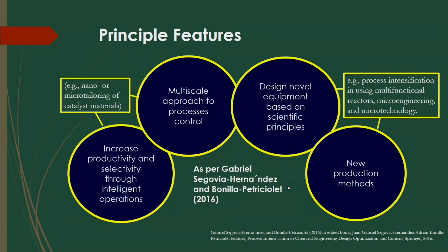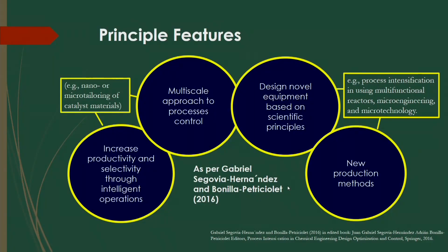And for process intensification, another important feature is the design of novel equipment based on scientific principles. Sometimes you can design some equipment in such a way that it will give you the best productivity of the processes, like nowadays micro reactors are coming. So, micro reactors, micro channel based reactors, where the gas liquid reactions will be done through that micro channel, even extraction processes, liquid extraction through the micro channel based reactor.